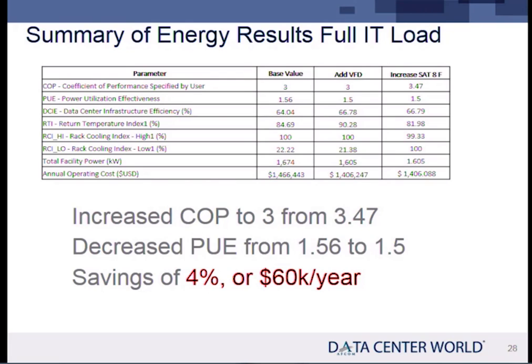and that makes your chiller more efficient, your heat rejection, whether it's a chiller or a DX, or an evaporator, or an economizer. If it's an economizer, the window opens. Because now my heat rejection temperature is higher, so I have more days of the year the economizer will run. In these examples, I'm assuming only mechanical, no economizer at all. If that unit, which is popular now, when you buy a new Liebert unit, they generally have built-in economization schemes, which means that window opens. So I have more days of the year that I can use it if I return hotter air to the unit.